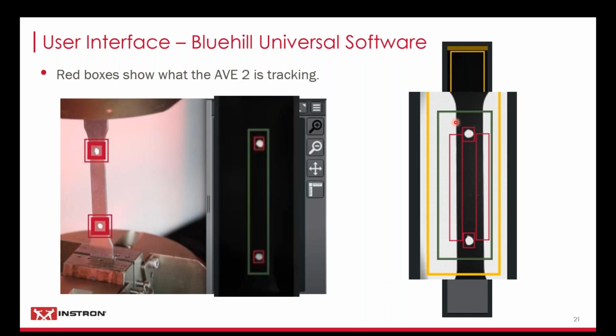You will notice we've got a specimen here with a white background, and that's because we're illuminating the back of the specimen as well, so we can get a nice contrast to those edges. On the left side, we do not light the back of the specimen typically, and our cross-polarization routine between the lighting and the lens allows the specimen to simply vanish into the background. So all you see is white marks floating in space, which gives us excellent contrast.